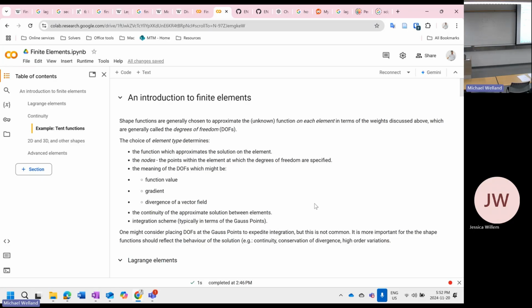You want to match that to the type of physics that you're doing. Curl elements are going to be good in electromagnetics, excuse me, right? Bubble elements have to do with that divergence term. So they're good for anything that's conserved, right? For elasticity, you have wave equations. Maybe you want to do a spectral method because that's a wave, right?